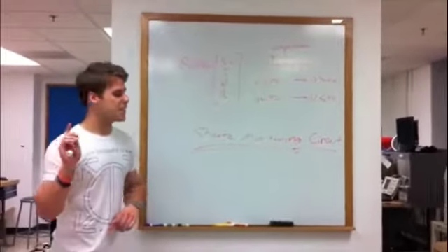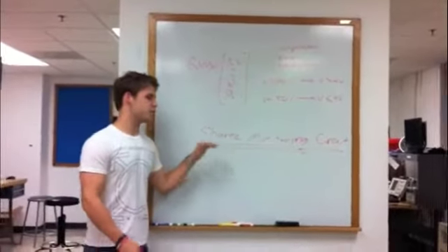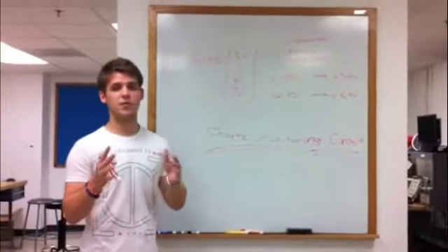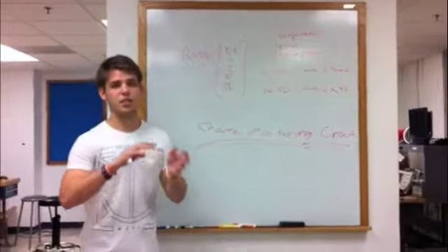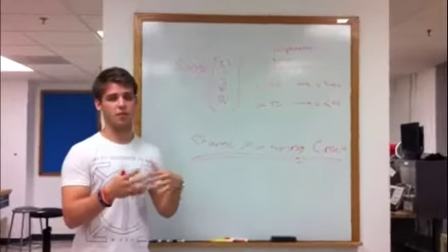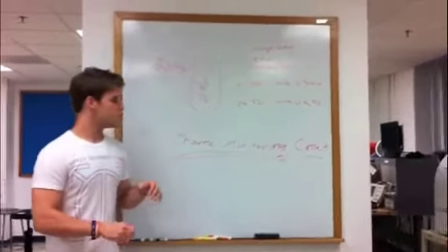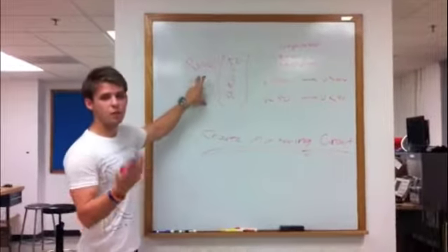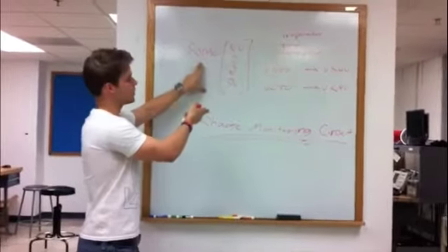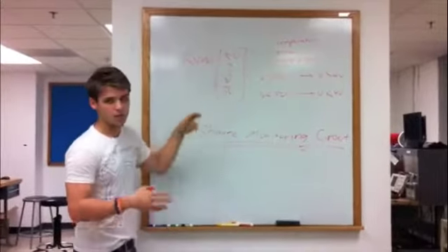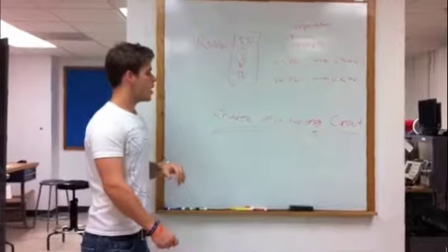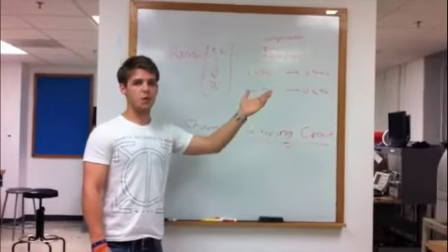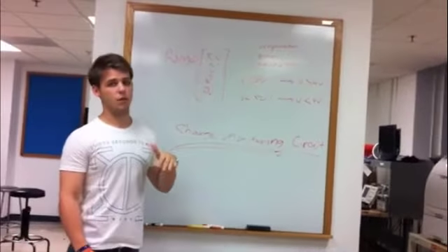Okay, so the third part of our circuit is to create a charge monitoring circuit. Basically, the idea behind the charge monitoring circuit is to keep track of how much our capacitors discharge voltage into the white LED, or the illuminating circuit. The basic idea that we have here is that the LED will run between 5 volts and 3 volts, which is the top and the lowest point in which the LED will be lit. How we keep track of this is that we have an above 50% qualification and a below 50% qualification.